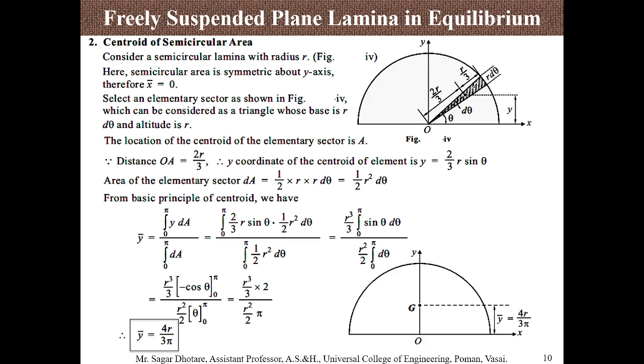And the y coordinate we find is y bar equal to 4r divided by 3 pi. You just need to understand the standard geometries and their centroid locations.